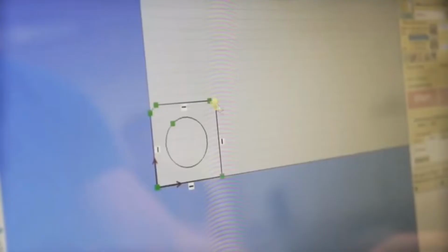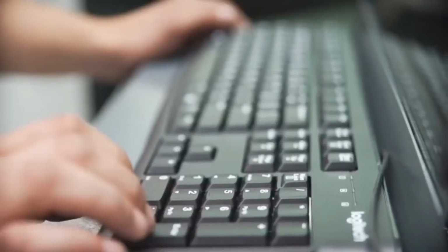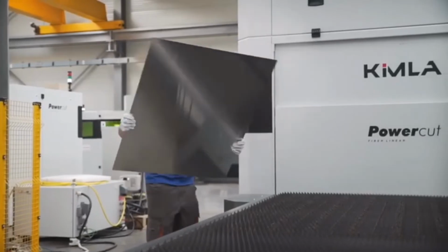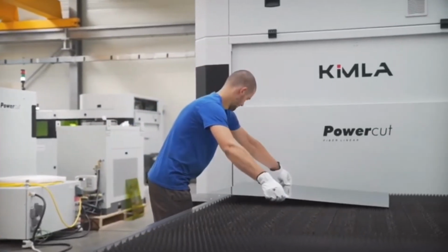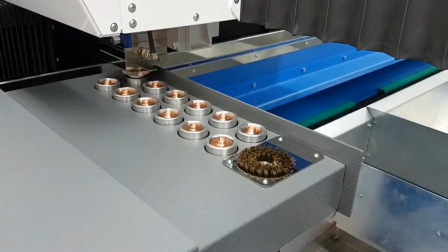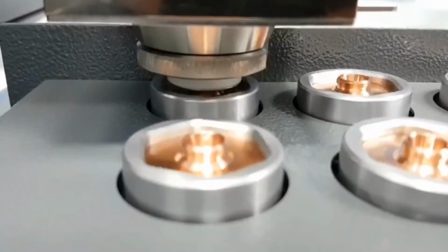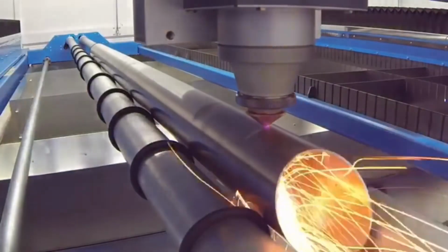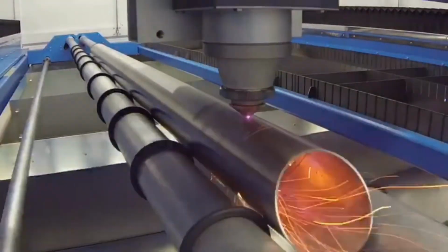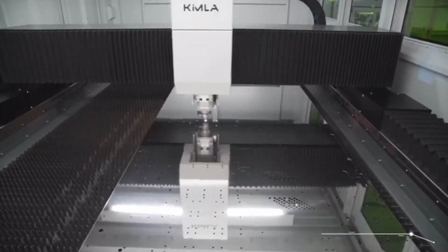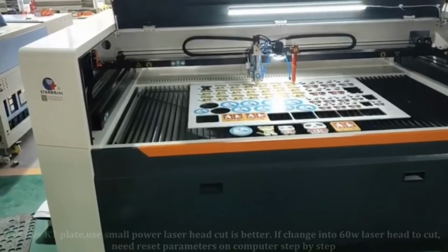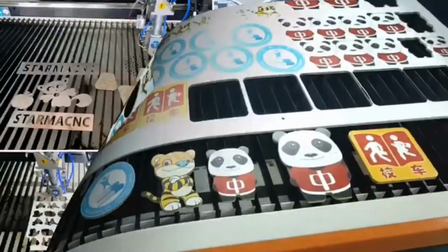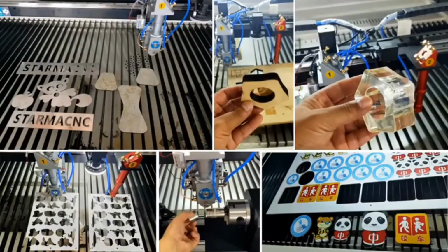Firstly, we have to design and transfer data to the monitor of the laser cut. After that, clamping the material tightly and turning on the laser cutting. In a laser cutting device, it all starts with the laser resonator. This beam of parallel light waves is reflected off one or more mirrors in the focusing head. It then passes out through a nozzle and sears whatever it lands on. Laser cutting gives a lot of design freedom, plenty of material options and can be combined with other methods giving you the best result.